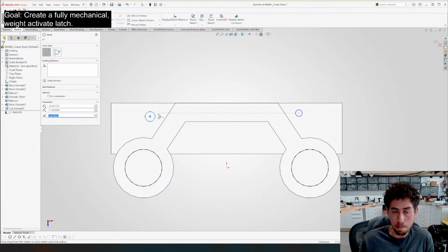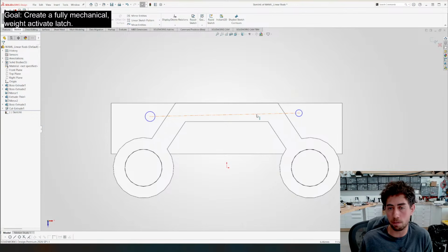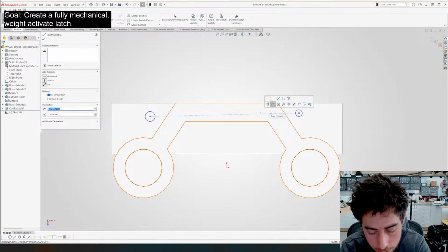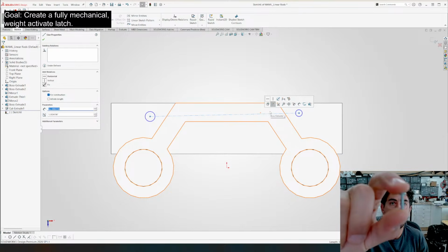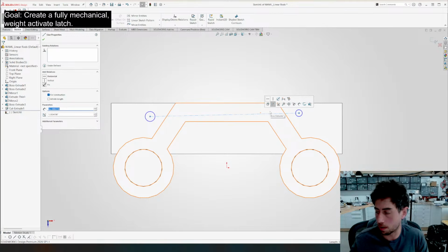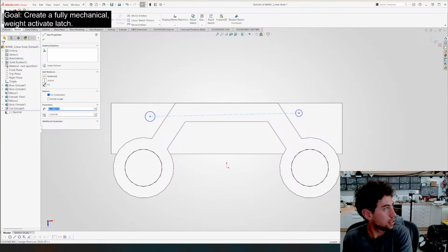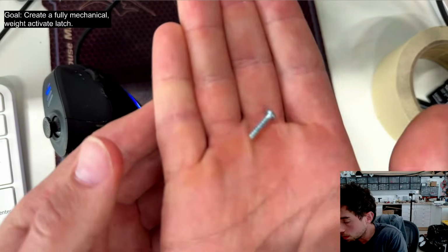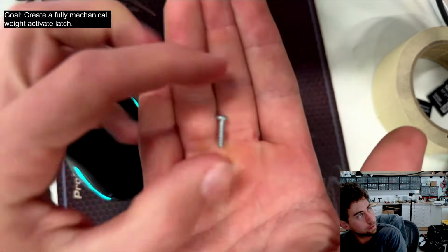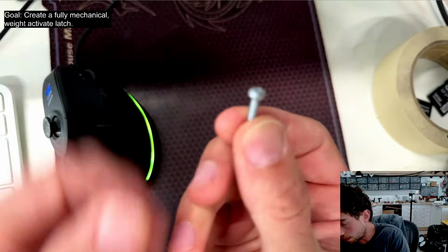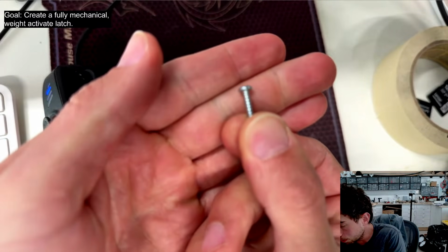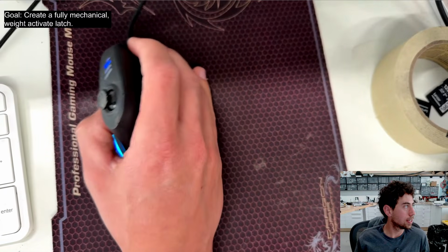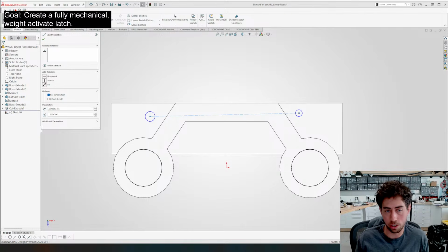And I bounce around with the hardware that I use, but for the most part, I really like to use these number 4 screws. I don't know if you can focus. Okay, I'll show you on this camera here. These number 4 screws, which are thread-forming plastic screws. So on a 2.75 millimeter hole, which always ends up being smaller because of the way things print, it ends up being perfect. And then I'll show you the clearance hole for that after.